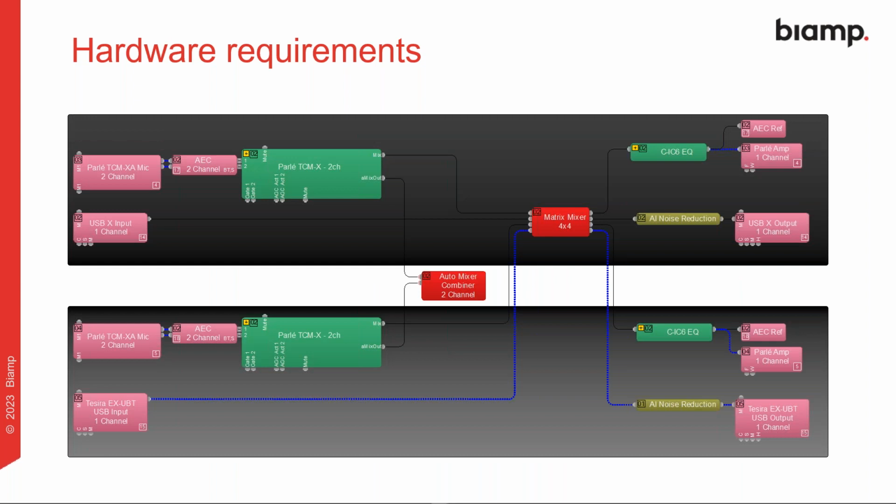And while we're talking about hardware, there's an example that I'd like to give, because we've had a few calls about this already. If you look at this example system, this is your traditional small divisible room, so it can go into two or in one, and we've got 4 microphones, and we've got the USB output of the Sierra Forte X running one room when they're separate, and we've got an XUBT which runs the other one when they're separate. We've got a requirement for 4 AEC channels and 1, 2, 3 AVB PoE ports.